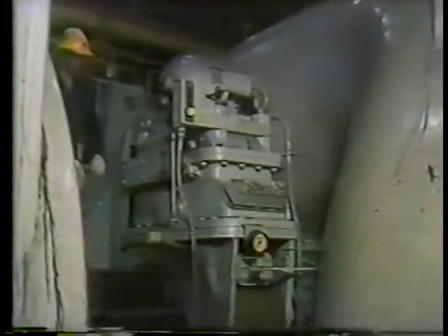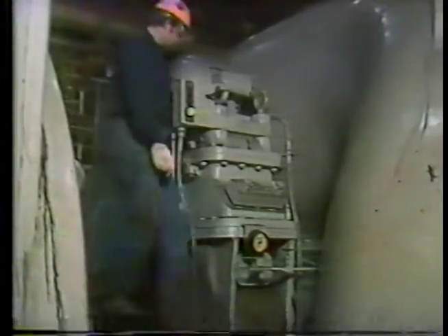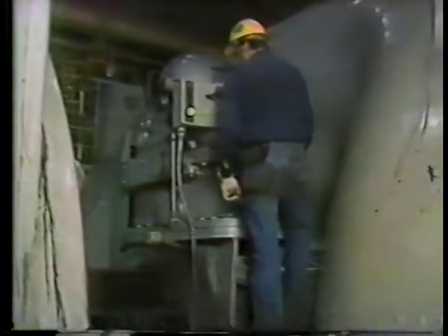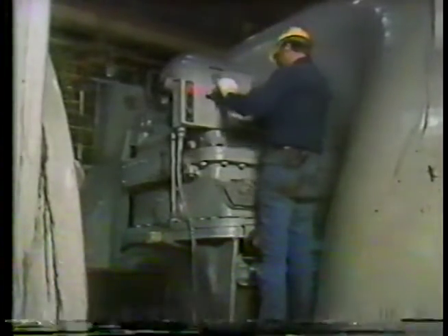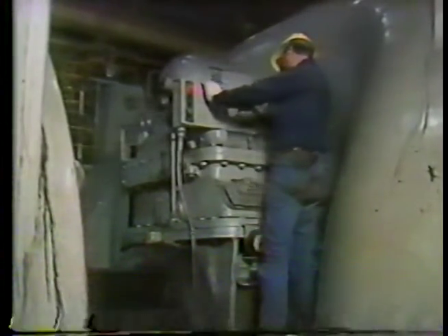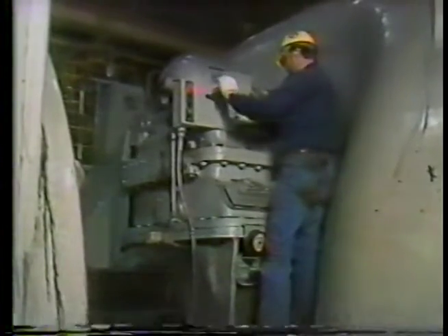The turning gear motor is started and the gears are engaged when the turbine coasts down to a standstill. This motor can be started manually by the operator, or in some cases, automatically by a speed sensor. Normally, the rotor is kept turning even when the turbine is completely cooled and no longer in operation. This is done to keep the rotor from sagging due to its own weight.